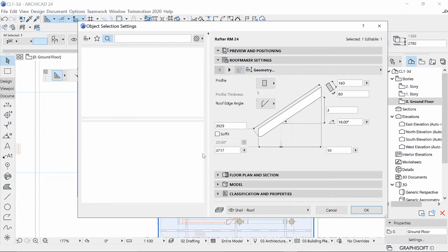Because you're going to have overlap, and the length of this truss is 4 meters, I'm going to use sheets such that one point somewhere around here is 2 meters, and the remaining part can be 2.5 meters. So if one sheet is 2 meters and the following sheet is 2.5 meters, the total becomes 4.5. 2 plus 2.5 gives you 4.5. If I take out the overlap, I'll remain with something close to 4.3, which is not bad. Or you will cut out some parts as waste. You always have waste when you're doing roofing anyways.